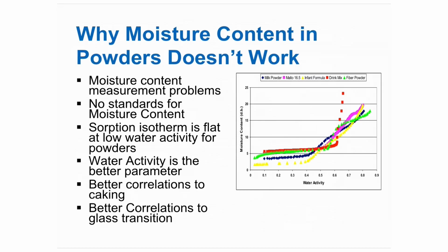And there's no standard for measuring moisture content, which makes it difficult to know if you're actually getting the right value in a consistent manner. The other is that, as you can see visualized in the figure on the right, these are moisture absorption isotherm curves for powders.